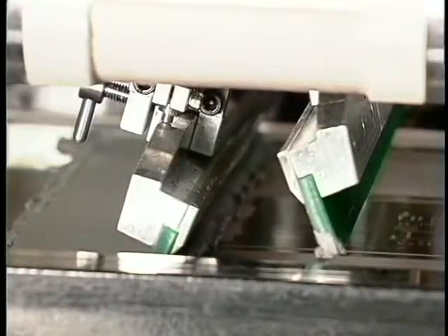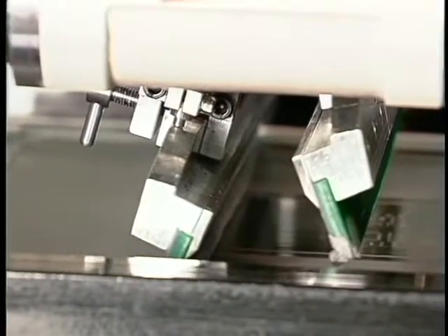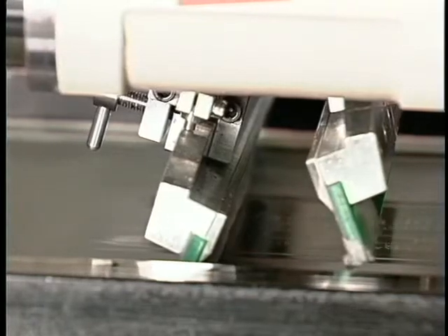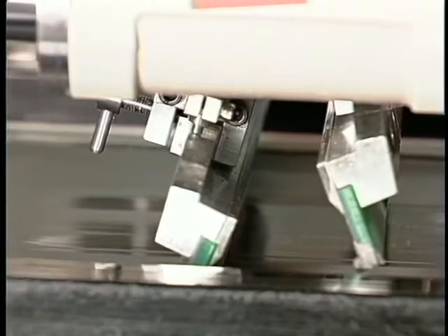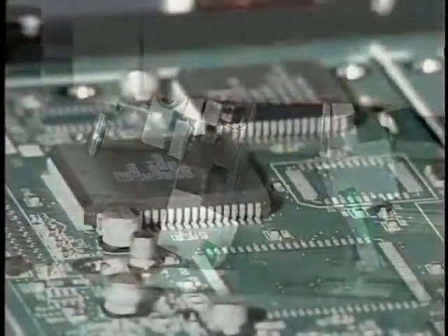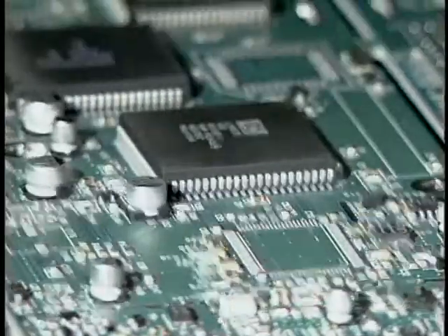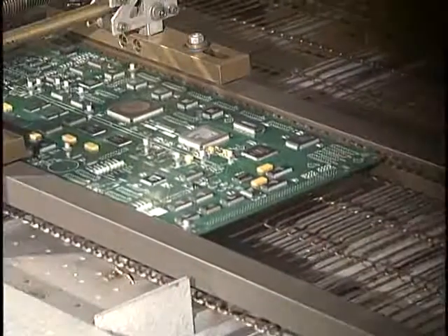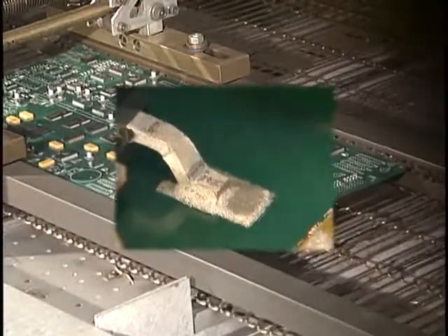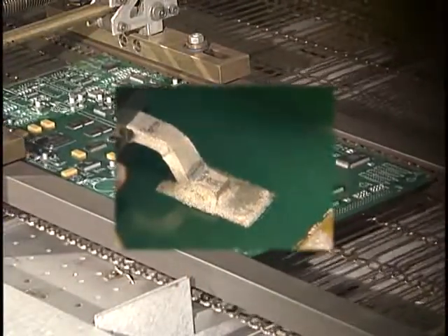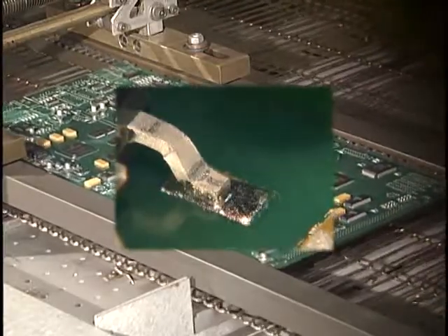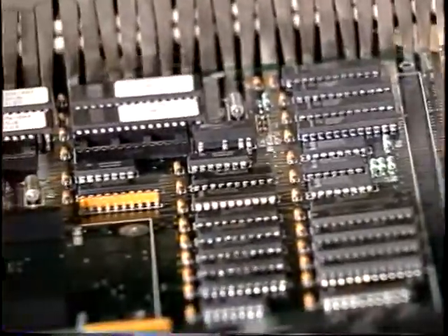In surface mount technology, the first step is to print solder paste through a stencil or screen onto the lands of the printed wiring board. The components are then automatically placed onto the lands containing solder paste. The components are now soldered to the lands in a reflow oven, which melts the solder paste to form the interconnections. Many assemblies contain both through-hole and surface mount components, and will undergo both wave and reflow soldering.